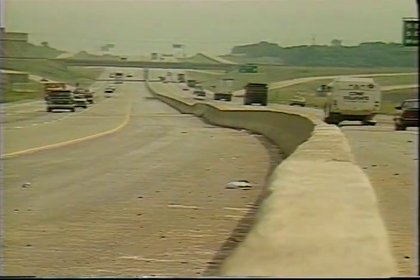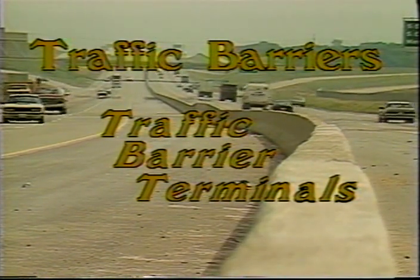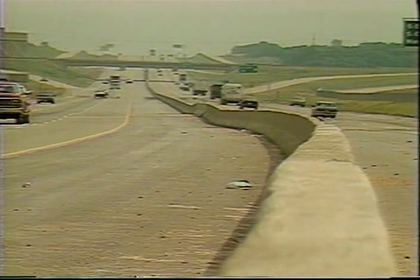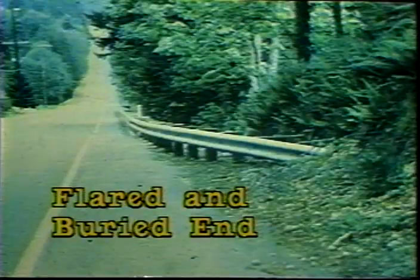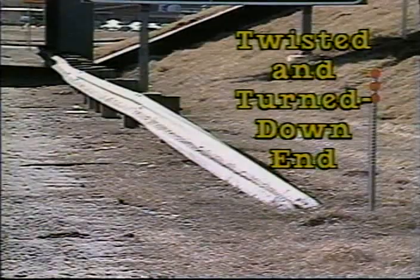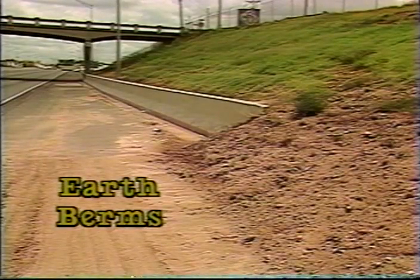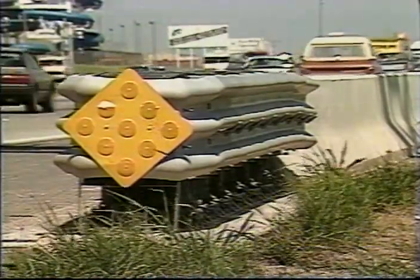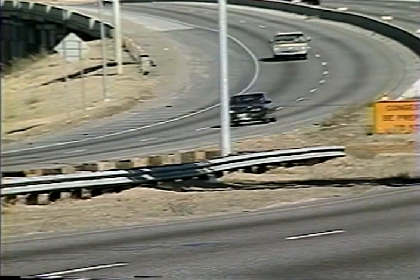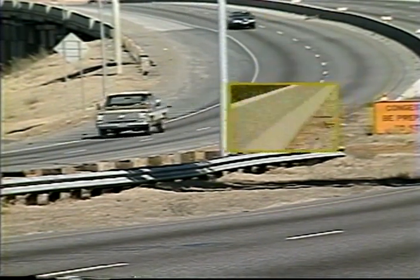In the final program, the installation, maintenance, and repair of various kinds of end treatments are reviewed. The program highlights these different designs: the breakaway cable terminal, the flared and buried end, the twisted and turned down end, the sentry system, earth berms, and crash cushions used as end treatments in different situations. Before discussing these programs, let's review the general purpose and function of barrier systems.